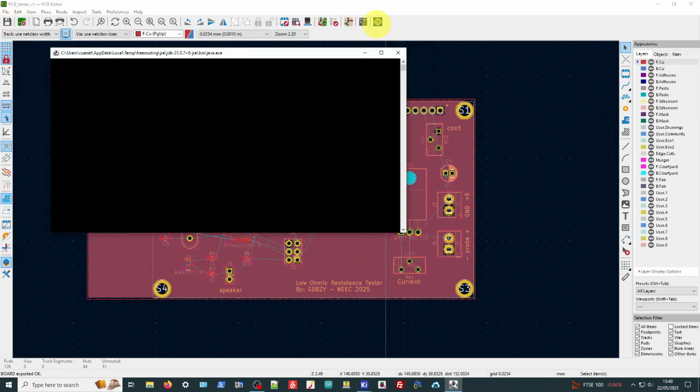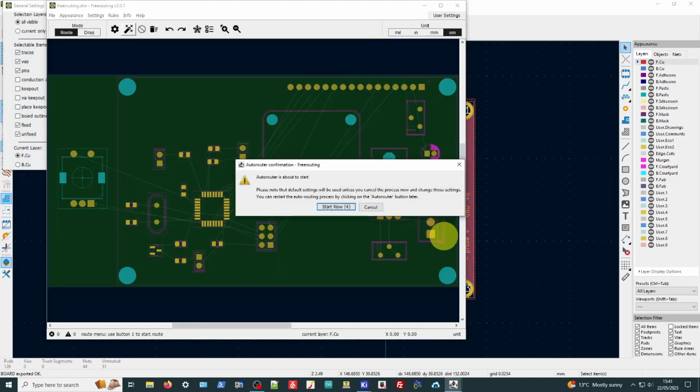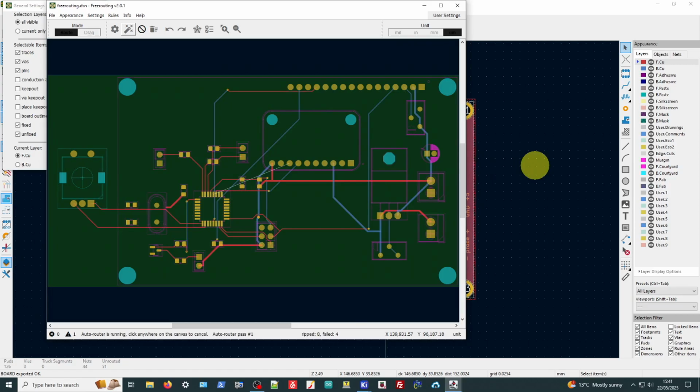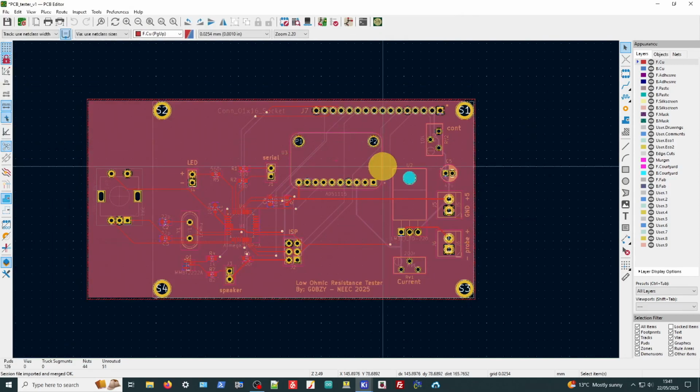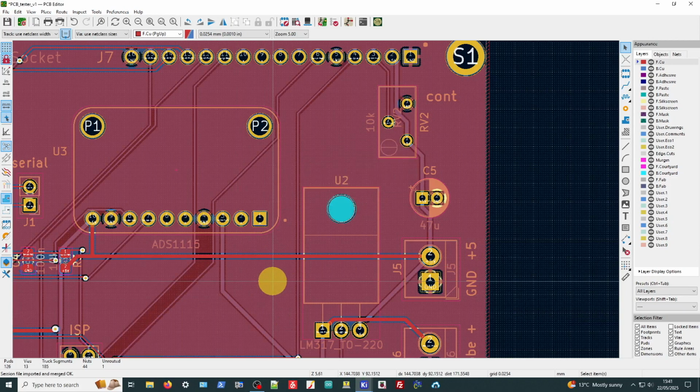Click that, and it's now loading in the PCB, and we'll tell it to continue. And of course we have got the class widths set up for the positive power rail, and there you go. Now what you'll notice is all of the copper is shorted out. There's no gaps or anything between the copper fill and the copper track, so we have to press B, which basically does another fill all zones. Let's do that, and there we go.